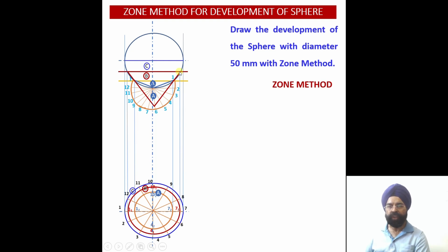So therefore, these slant edges, outermost ones, they will represent the true length of the slant edges over there. So this one, you see, starting from here up to this point, this is my complete length of the cone, uncut cone, and this is the length for the cut cone over there.